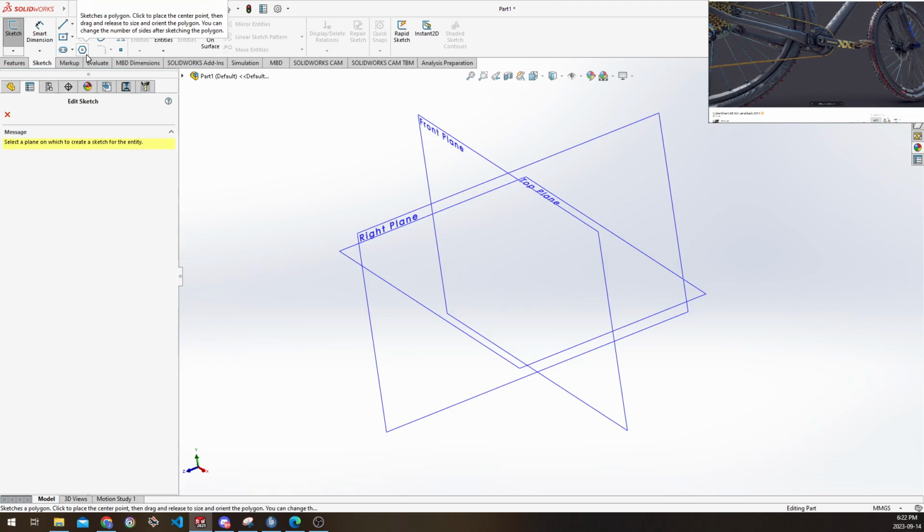We also have hexagons and stuff like that. For example, when we do 3D prints, we will tend to include a hexagonal hole in the 3D print to allow a nut to be placed into it, so we don't need 2 wrenches basically to put a screw in. Ease of life thing, but it takes 5 seconds to do in CAD, and it reduces a lot of physical strain from taking screws in and off in person.